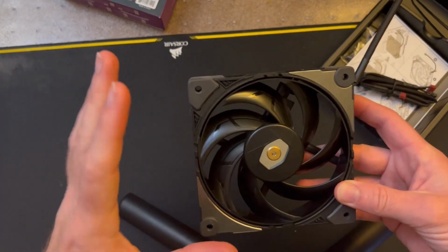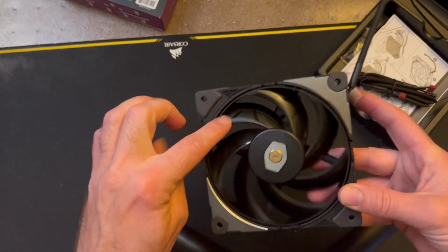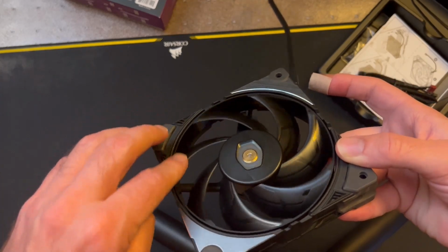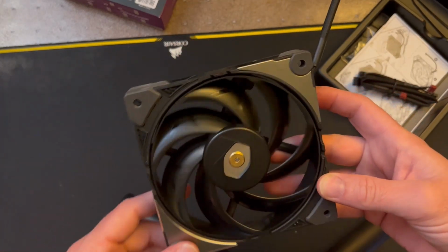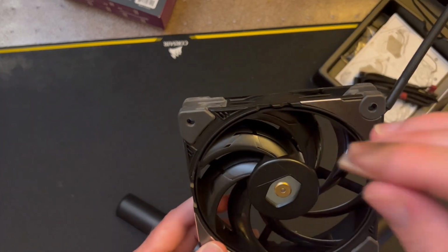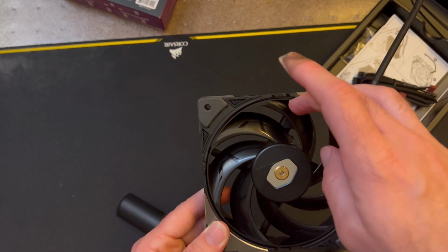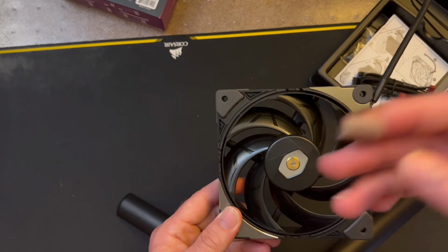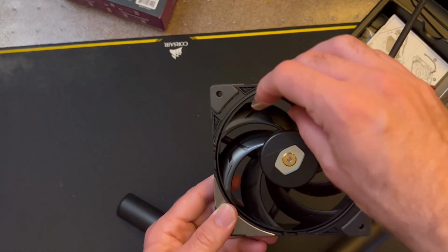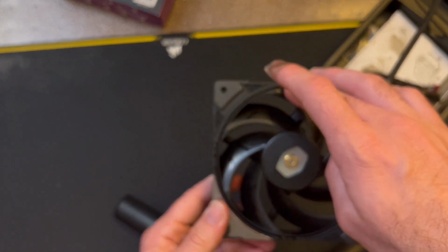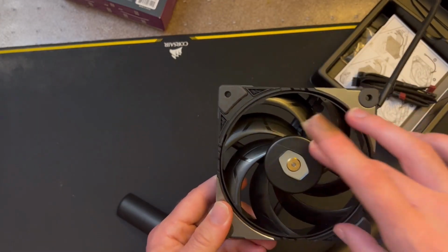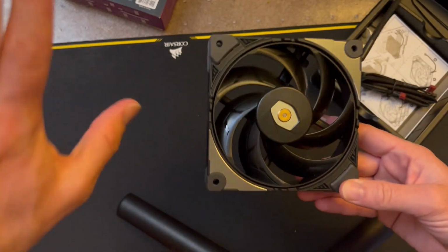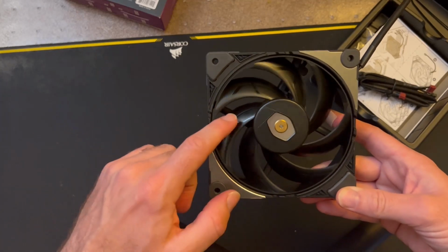So now let's zoom in onto the fan blades themselves. This is a fan that has a ring around the outside. So right there, I don't know how well it'll show up, but the whole fan is in a ring. So what does this mean? It means there's no gap, effectively. Mind, there is a gap between the ring and the outer housing. But over time, cheaper fan blades will tend to stretch and eventually start ticking against the side. That is unlikely to happen with a ring. But mind, if the rotor is not centered properly, you could still get ticking, but that's a different topic and less likely to happen.